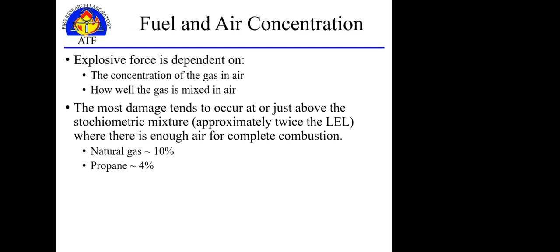The fuel and air concentration is going to be a function of how much gas and air there is. Is it at the low end? Is it up on the high end, or is it rich? And how well that gas is mixed in the air are going to play a role in how violent that explosion will be.